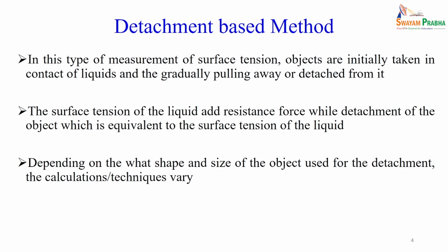In this detachment based method, as I told, we initially put objects into contact with the liquid and gradually pull them away from the surface. If you put it in contact and pull away, you require some additional force, and that force is exactly equivalent to the surface tension of that particular liquid.